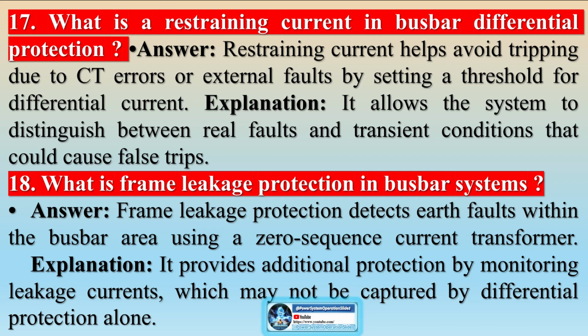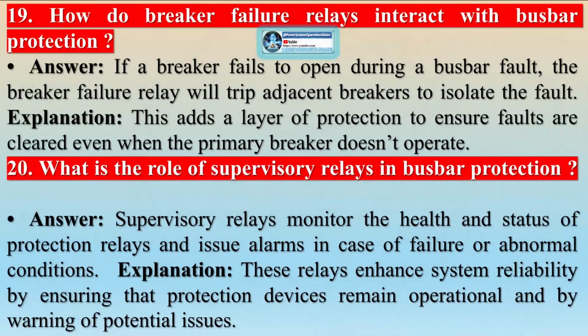Requirements for direct tripping: remote end of a 2-ended feeder connected to a double busbar substation. Remote end of a 3-ended feeder connected to a double busbar substation where fault clearance and CB fail time is unacceptable. Local substation indoors with CTs on the line side only. Outgoing feeder is a transformer feeder with LV side circuit breaker at the remote end. Local SGT LV circuit breaker connected to LV side kV at the local end. Situations where CB fail protection delay affects generator stability or continued energization from the remote end is unacceptable. No requirement for direct tripping from bus sections or couplers.